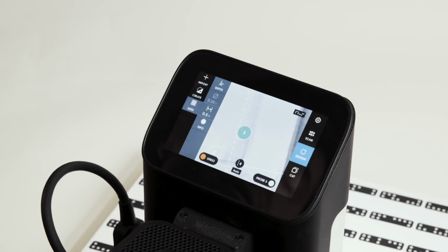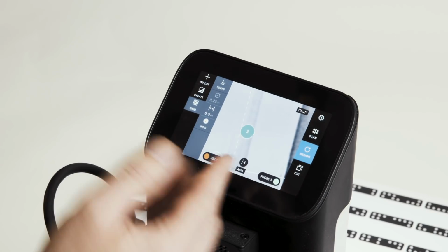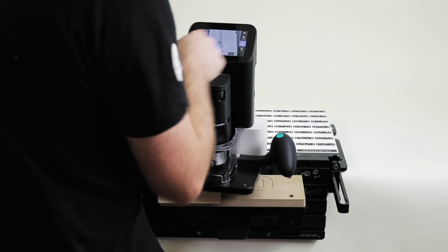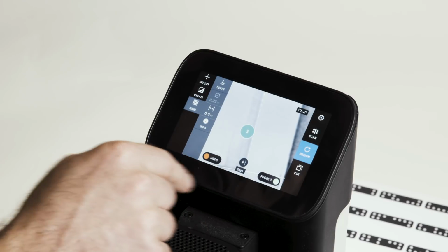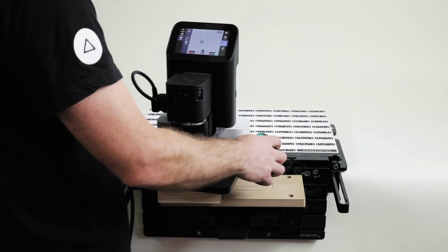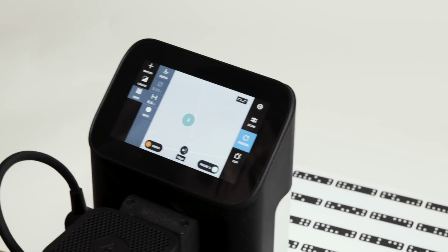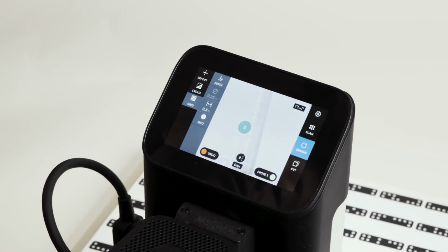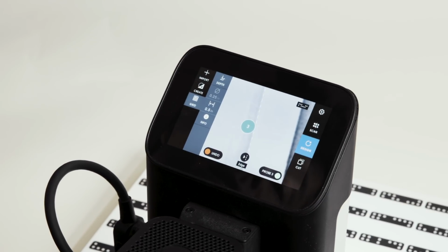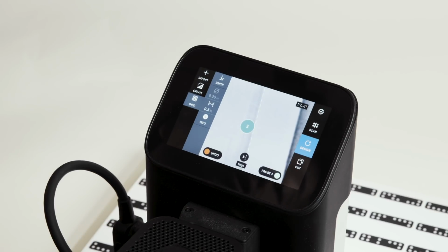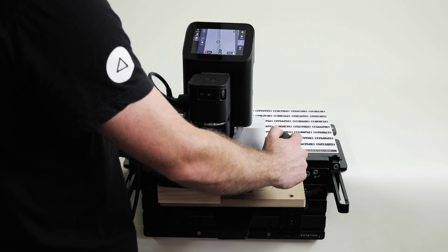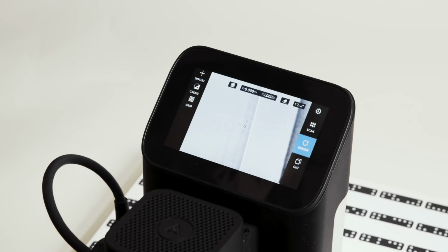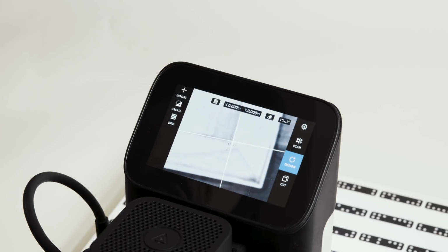Now, same thing happens. We're in auto mode here. It's assuming I'm probing on the left-hand side of the probe. I'm actually probing on the right, so I can override that as well. Centered, right. And once you override it, it remains locked. It doesn't try to automatically guess for you. So it should make things nice and quick for standard probes and leave the door open to adjusting for more non-standard probing arrangements. So probe the right-hand side, third probe. And now we have a grid aligned with this inside edge.